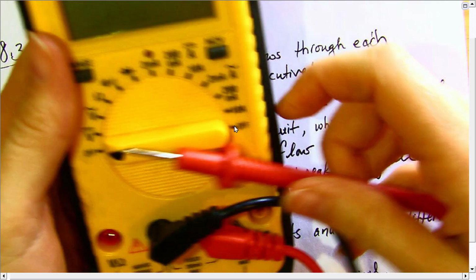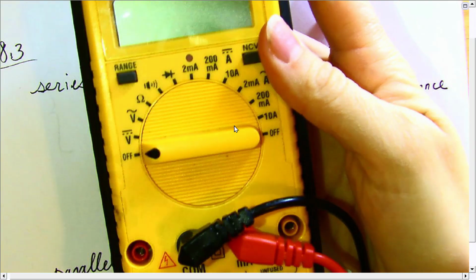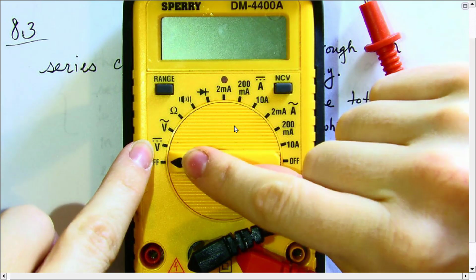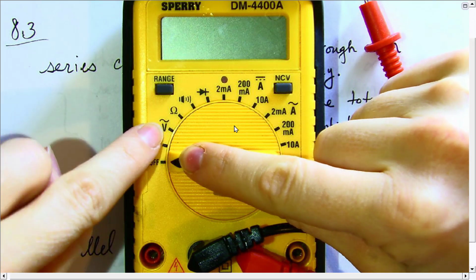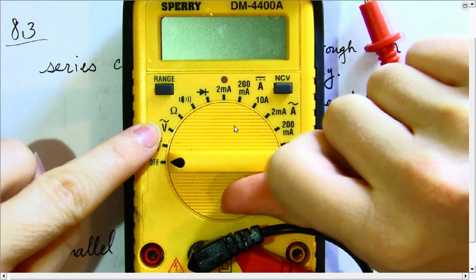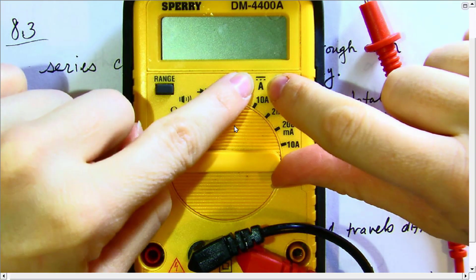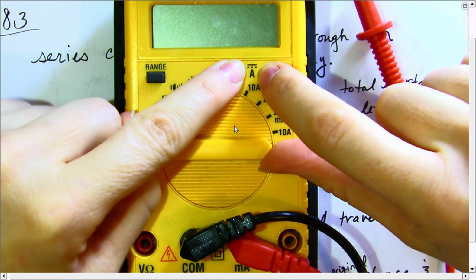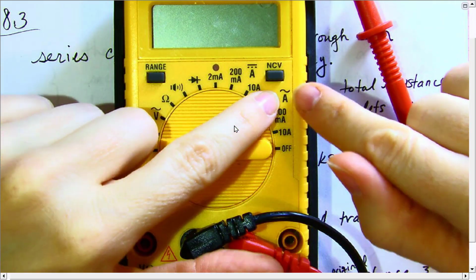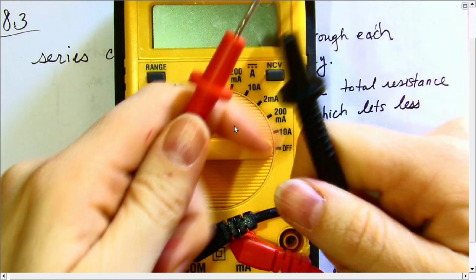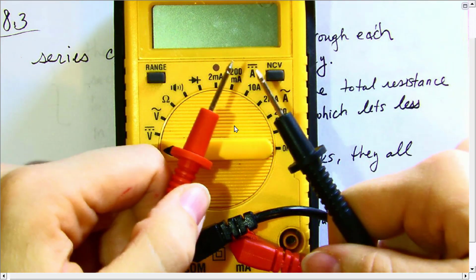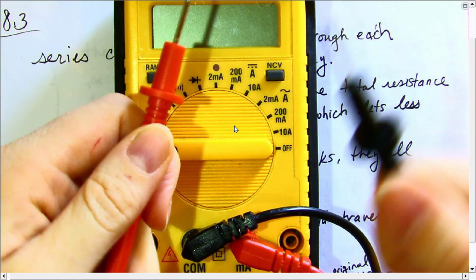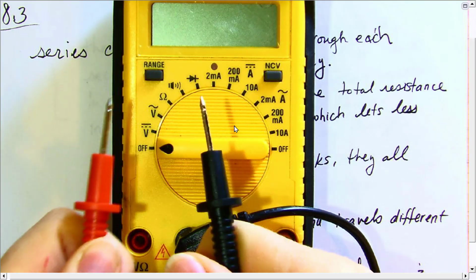Which is one reason why this multimeter of mine has so many settings, because it can measure DC voltage, but you have to change it to a different setting for AC voltage. You can measure DC current from like a battery or like a laptop or something, or AC current. All right, if you stick these into a wall outlet to actually see if the voltage is right, you would set it to AC voltage and then stick these into the outlet.